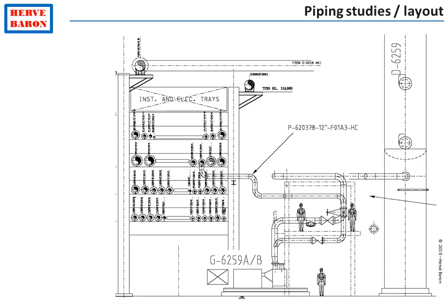Piping studies will also consider access for the operator to manifolds, such as the one shown here, the valves on the pump suction and discharge lines. Access to instruments as well. Straight lengths for instruments such as flow meters. All this will be considered while doing the piping layout.